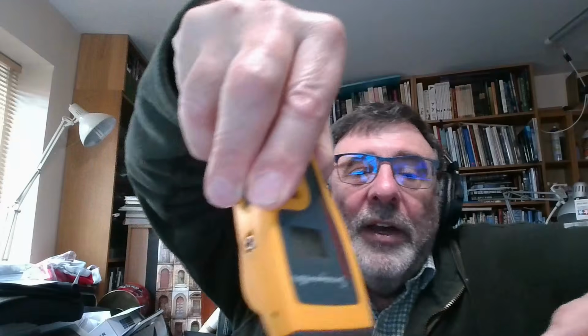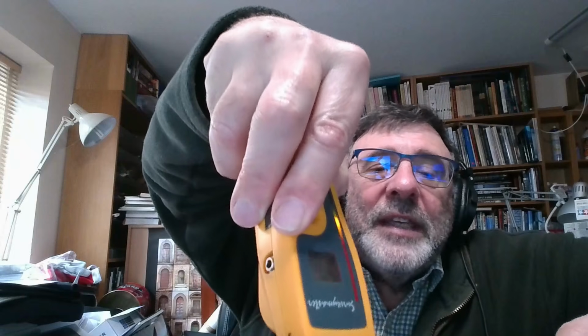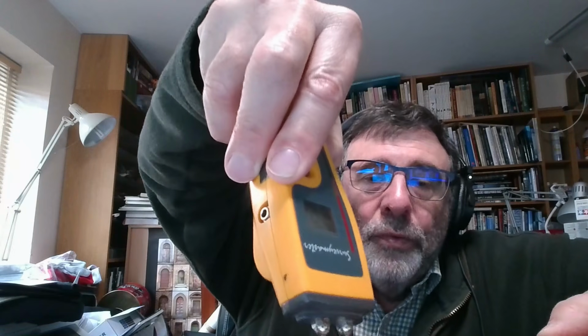What I'm going to do is sprinkle a little bit of salt on there as well. Let's see if that makes any difference. So I've now got a bit of wet timber with salt on it as well, just to confuse matters even further. Now, what's the reading I'm getting? Oh, it's turned itself off. Here we go. Now, all of a sudden, 89, you can't quite see that, 89%. It's suddenly gone up. That salt has caused it to go to 89%.